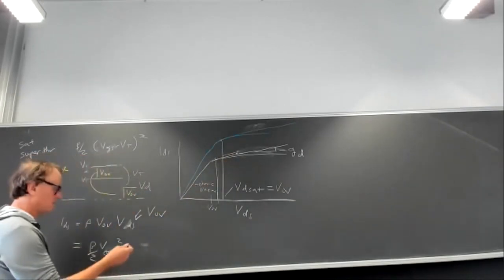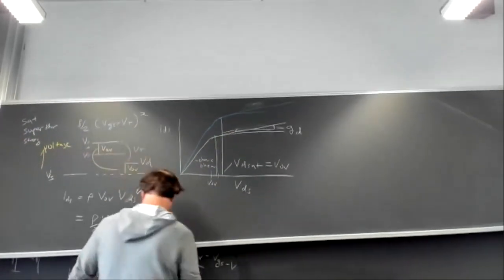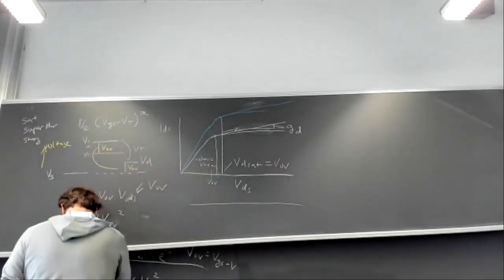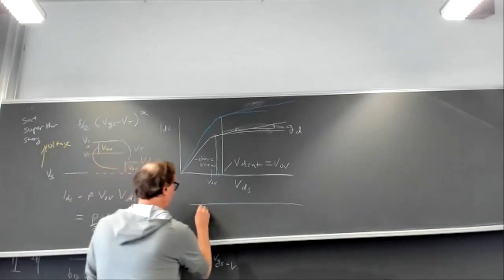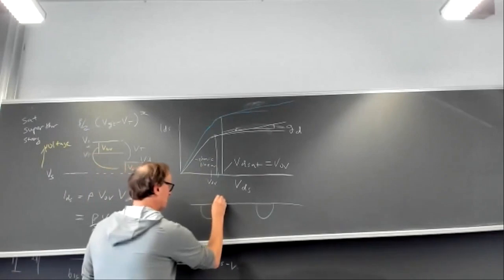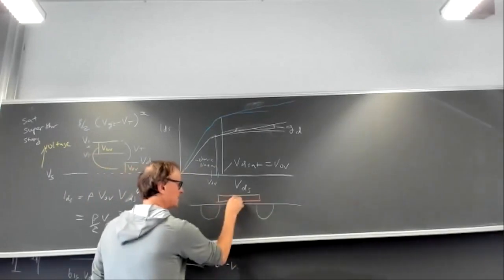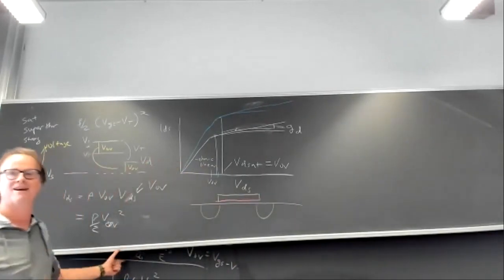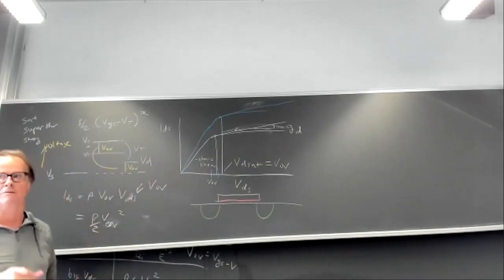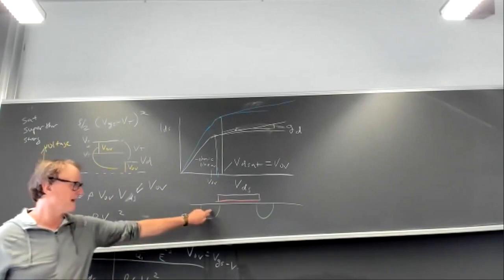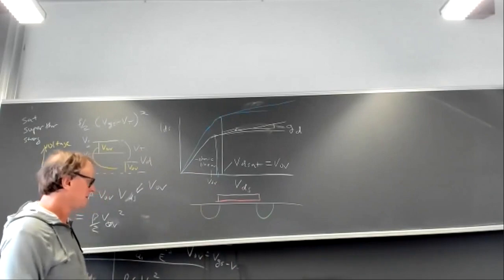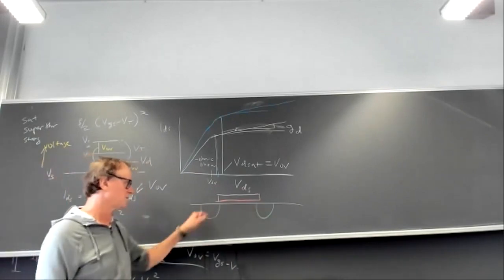Let's draw the cross section for reference. I'll just draw the cross section of the transistor down here again, so we can speak about it a bit. Let's draw green for the source. And by the way, you know why they use red for poly? Because when you look in a microscope, the polysilicon actually looks red. That's why they always draw red. And green: the active region kind of looks greenish in the microscope. This is called the active region, these doped regions for source and drain.